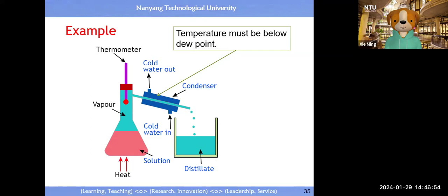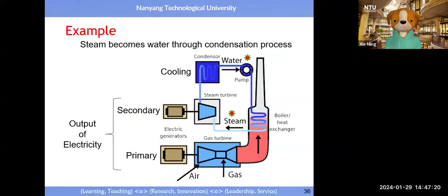Your input water will be very dirty, right? Then you convert the water into water vapor. The water vapor passes through a surface. The temperature of the surface is below the dew point. Then the water vapor will become liquid water again, and in this case, the liquid water is pure water, drinkable water, right? So this is something for you to know.